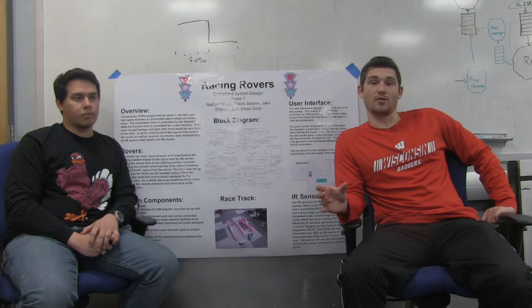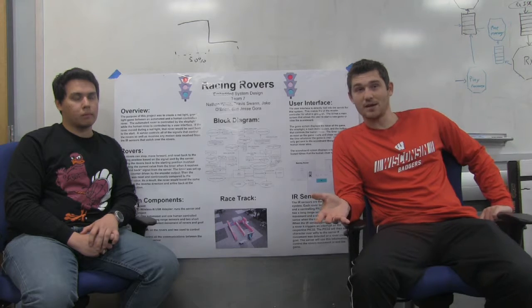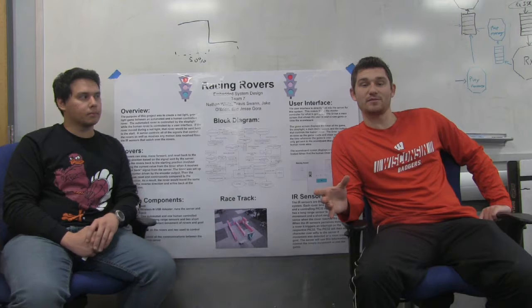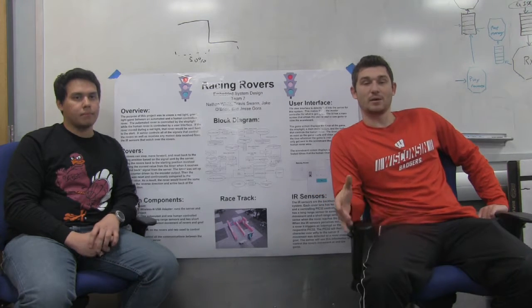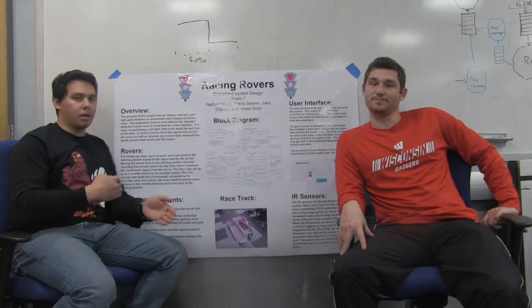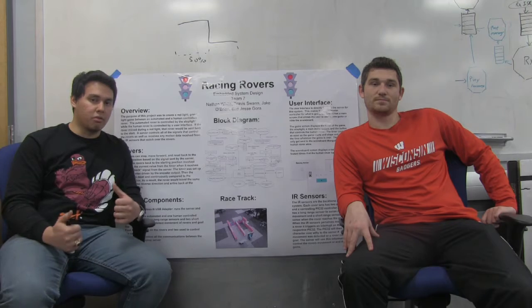Whenever we received a green light through the UART, so therefore through the Wi-Fi's, then we would send the max, or the 95% duty cycle, to the PWMs, and they would start going forward again. So after we were able to get a simple stop and go command, the next step was really getting the rovers to flip directions and go reverse.